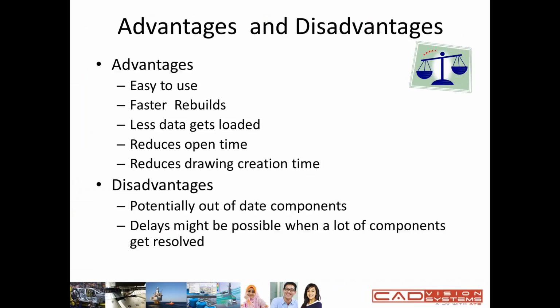So what's the advantage and disadvantage of lightweight? About the advantage, lightweight is really easy to use because you can set it as default, or right-click, just one button to set it to lightweight. It also gives you a faster review because it doesn't have the features in the FeatureManager, and also less data gets loaded because of no features. So the computer doesn't have to run all the features one by one. So basically it reduces the open time, and your drawing creation time also reduces.